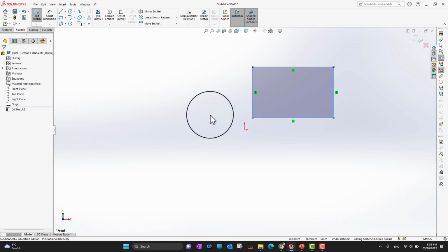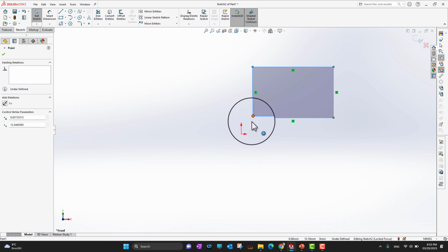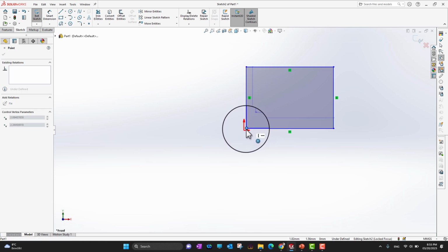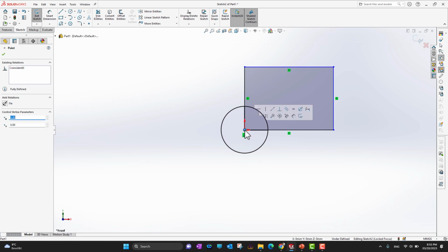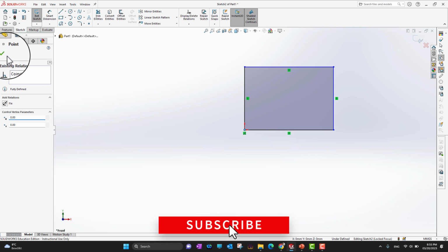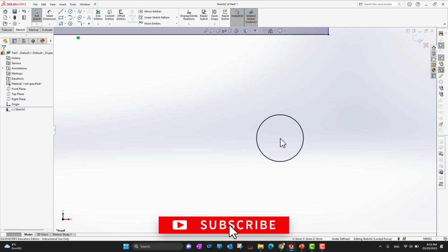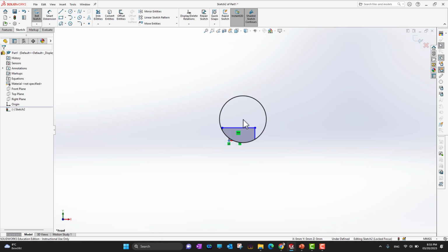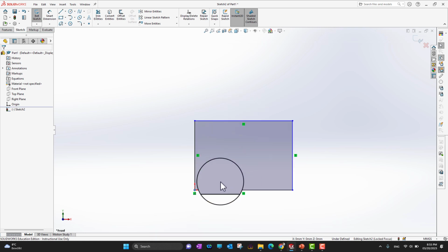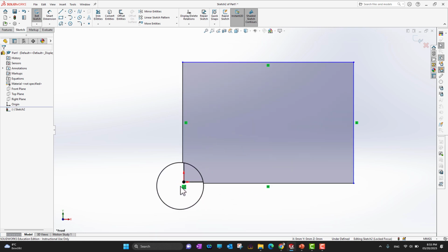And then second, we want to tie this geometry to the origin. What I'm gonna do is hold this corner and bring it to the origin of this coordinate system. In this way I can tie my sketch to the origin, and I'm not gonna lose my sketch anywhere. As you can see, I can go anywhere and you are not gonna lose it. It's always connected to the origin, so you can just find your origin and find your sketch easily.